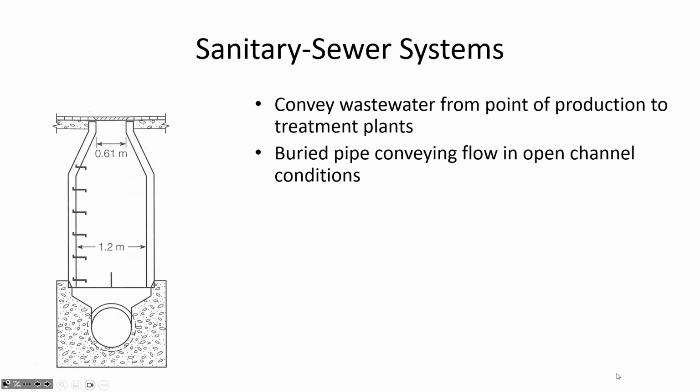Hydrogen sulfide. Sulfur dioxide is something separate. Hydrogen sulfide. So basically in sanitary sewers, what we have to do is hopefully provide a way for the wastewater to flow by gravity from people's homes towards a collection network. And it's often concrete pipes because concrete is resilient, lasts a long time, and is fairly resistant to corrosion, and it is also less prone to groundwater causing it to float upward in buoyant conditions. If the groundwater is above the sewer pipe, sometimes plastic pipes can be forced to the surface when the groundwater table is high.